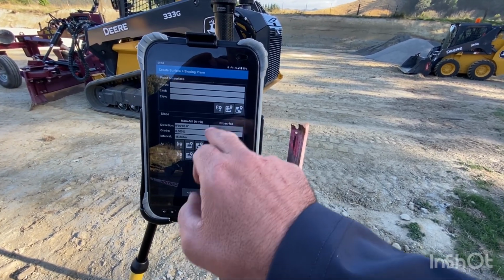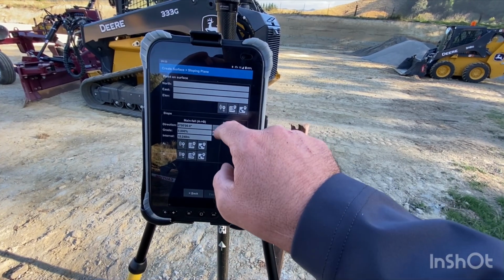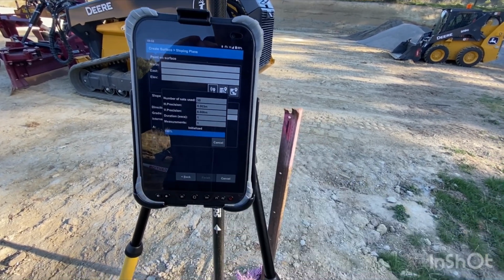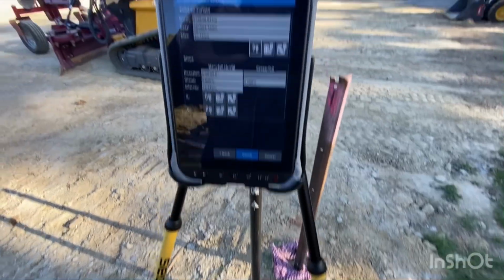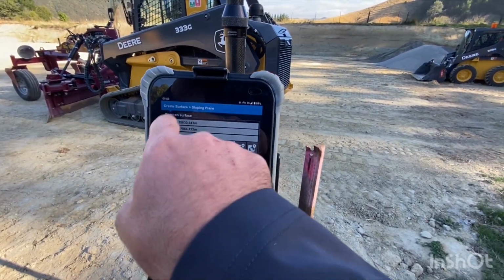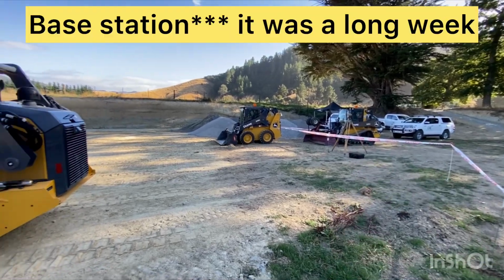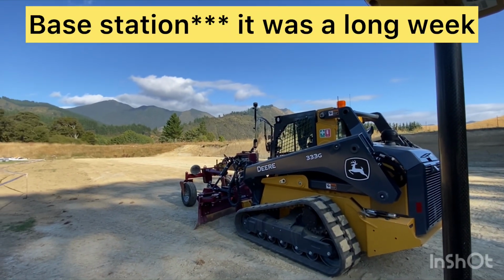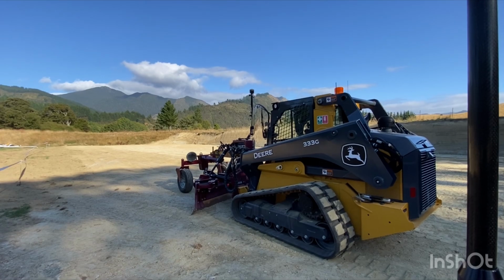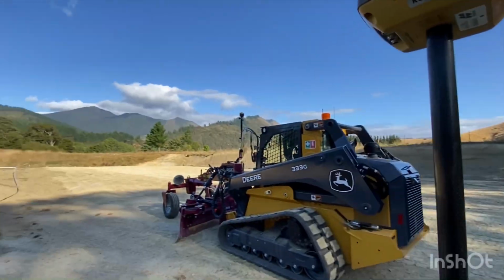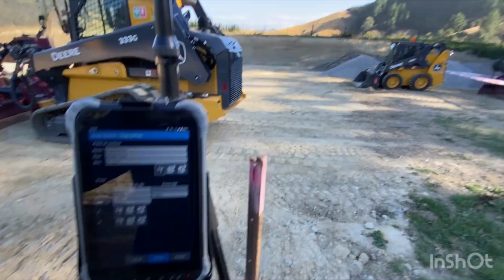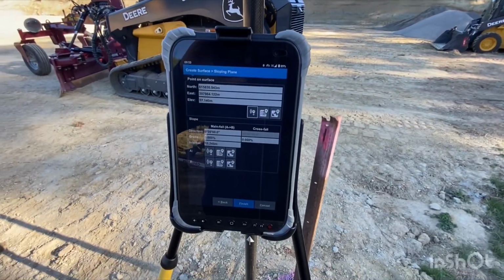So we're going to store the point there. It's just taking a shot down on my datum point, so it gives me a northing, easting and elevation. I've got this running off the total station at the moment, just to go out and use GPS, but we'll move into base station. We'll move into total station work a little bit later to run out that material on the top.